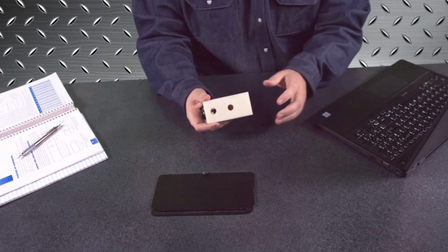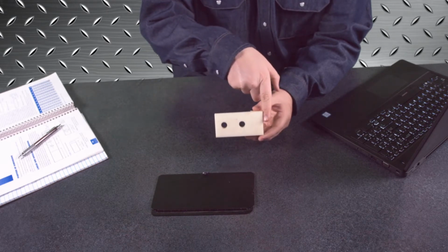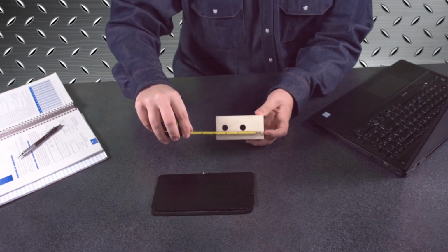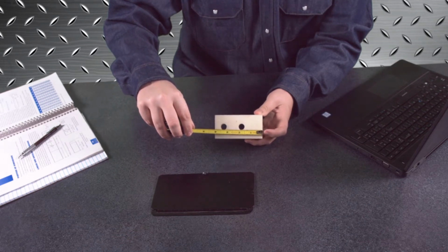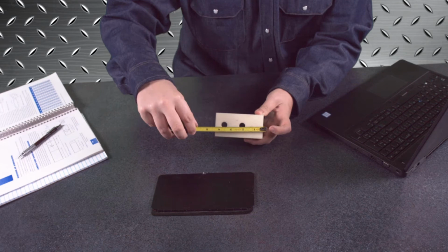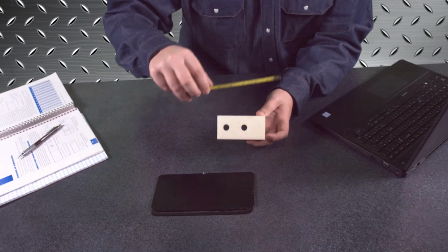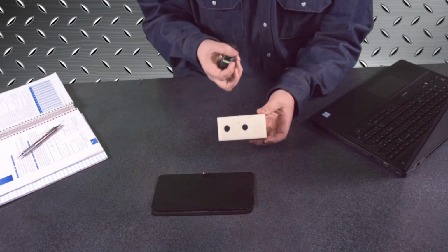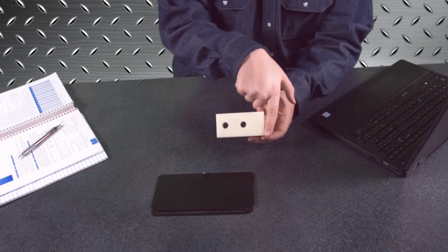Baseline dimensioning is a little bit more precise, because you're measuring everything from this point right here. So if I wanted to know these locations of these holes, I'd start from here and I'd pull my measurement here. So I'd go 1 1/2. And then for the start of this hole over here, I'd measure again from this point, and that'd be 3 inches. So everything's drawn from a baseline. So conventional dimensioning builds off of each other, while baseline starts from a single point.